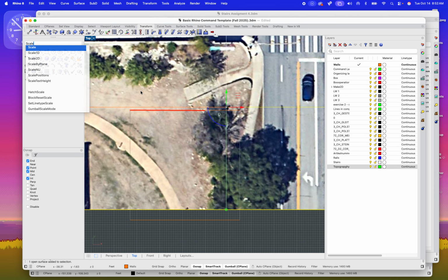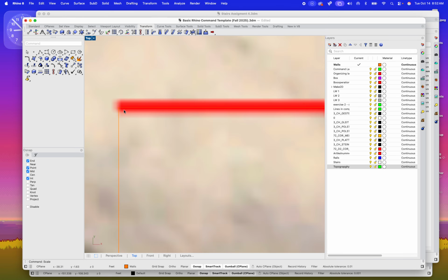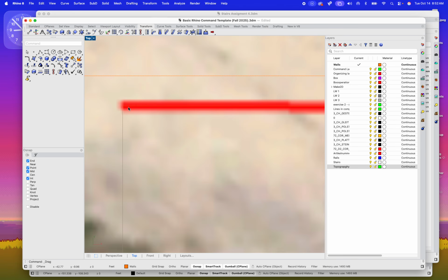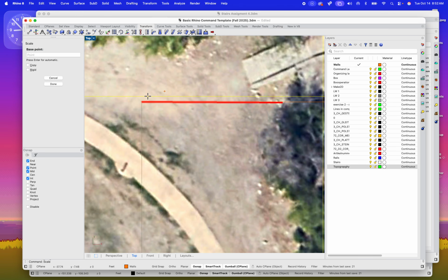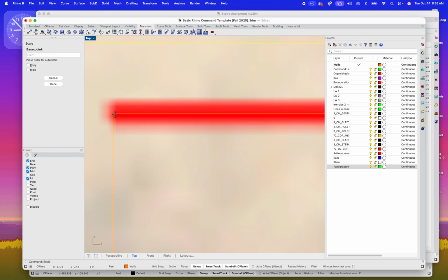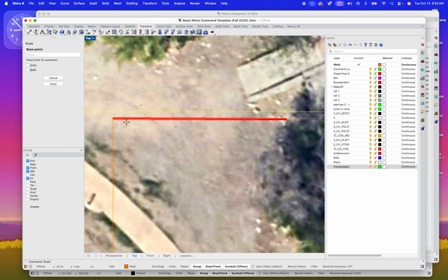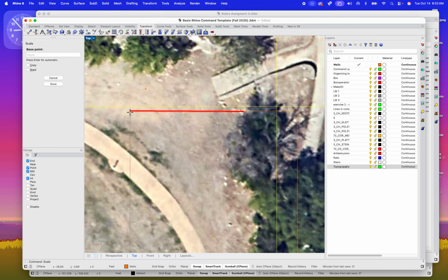In my case, I'm going to scale it. So type scale. It's going to ask for my base image. One thing I left out is, we want the end of our line to actually match up with the end of this rectangle. We'll take the image itself, scale it. It's going to ask for a base point, so that is the same point as our line and our reference point. And in my case, it's having a hard time finding the end point. So let me escape. Let's try that again. Find the end point. Please.